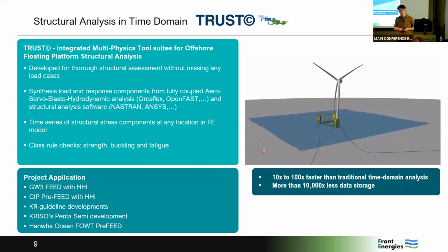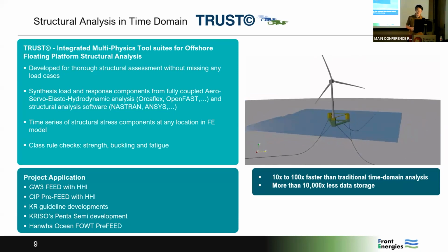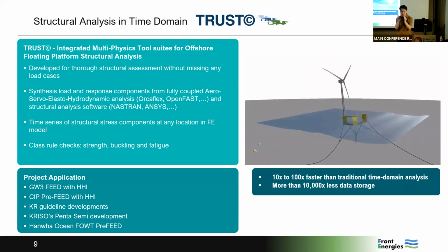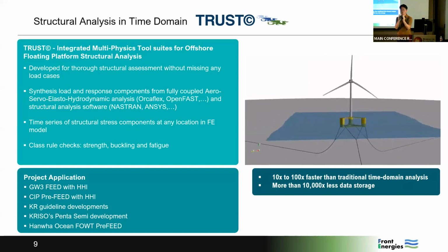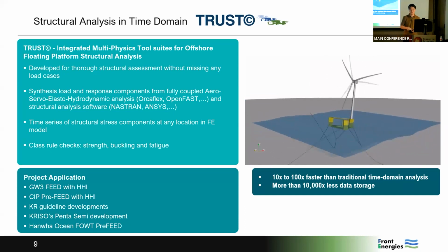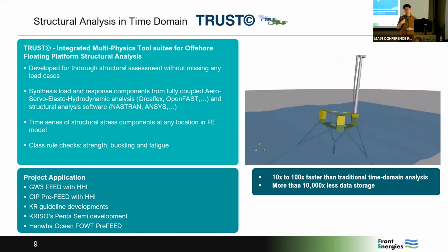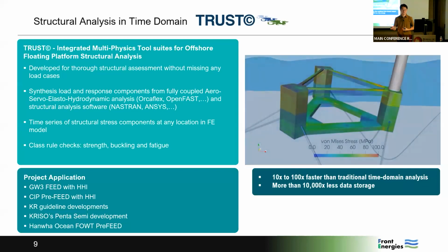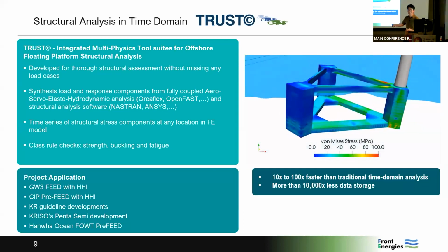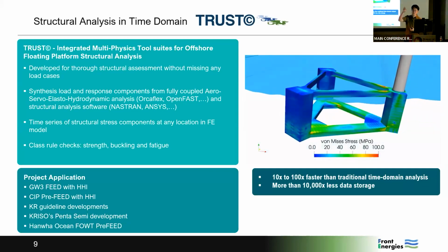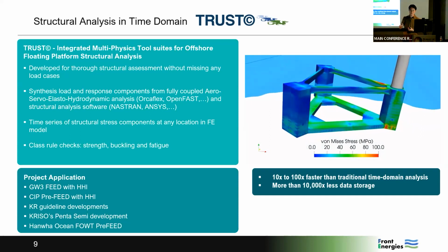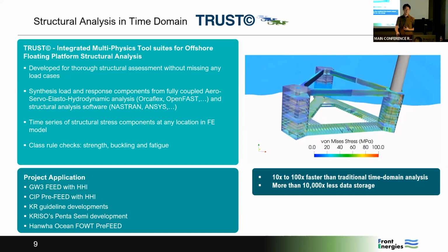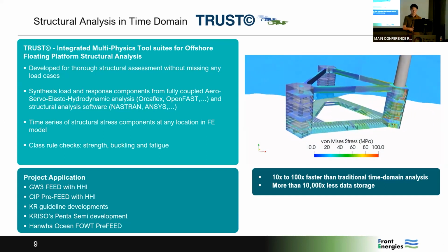Conventional time domain tools take a long time, so they pick a very small duration of the simulation for the time domain analysis. But we don't want that, so we solve the whole time series of the structural response. Through these tools, you can get a time series of the stress components for the whole duration of the simulation, like a 1 hour or 3 hour simulation.